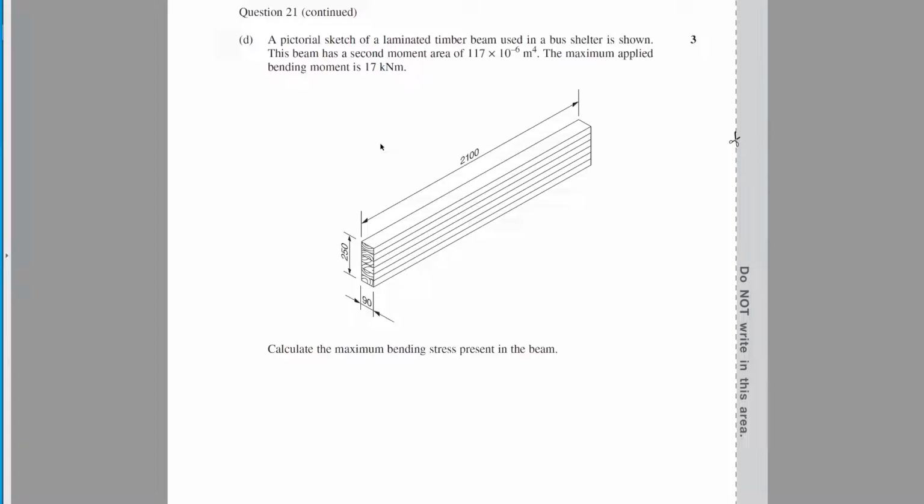But in this case, they've given us, now I sung the song before, we go together like megapascals and millimeters squared. They haven't given us millimeters here, they've given us meters. And it's very, very hard to convert this into millimeters squared, so we don't. We just use whatever units they've given us. So if they've given us meters to the power of 4, we're going to use meters to the power of 4.